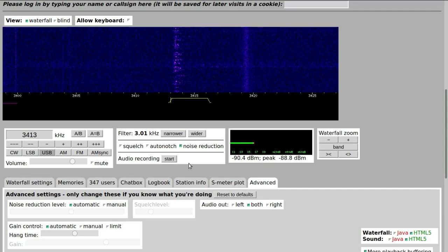Noise reduction on. Notice that the random noise has dropped in magnitude. Unfortunately, we are experiencing some gerbling and swishing in the background. That's because the signal is so weak that the LMS function in the noise reduction is having a hard time finding spectral components to craft filters around. It's making random estimates at anything that seems for a brief moment to be coherent.